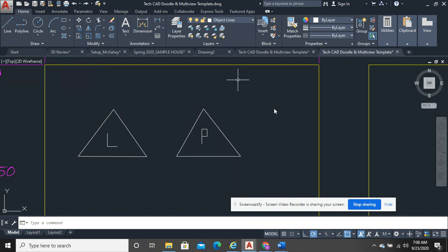Polyline makes things stay connected. Line keeps them unconnected. The points are still touching, but it's regarded as three different objects. This is regarded as one object from a code standpoint. Now, this takes us into our first modify commands.